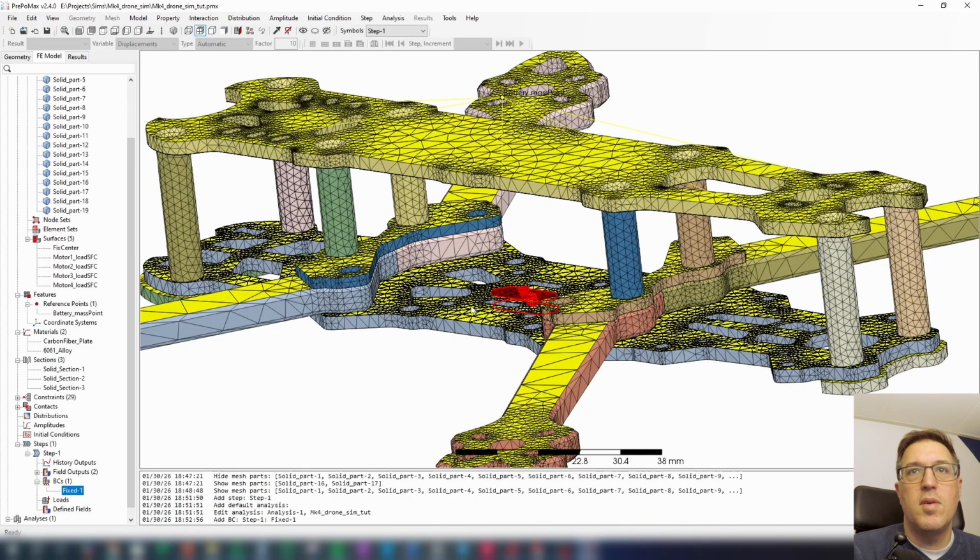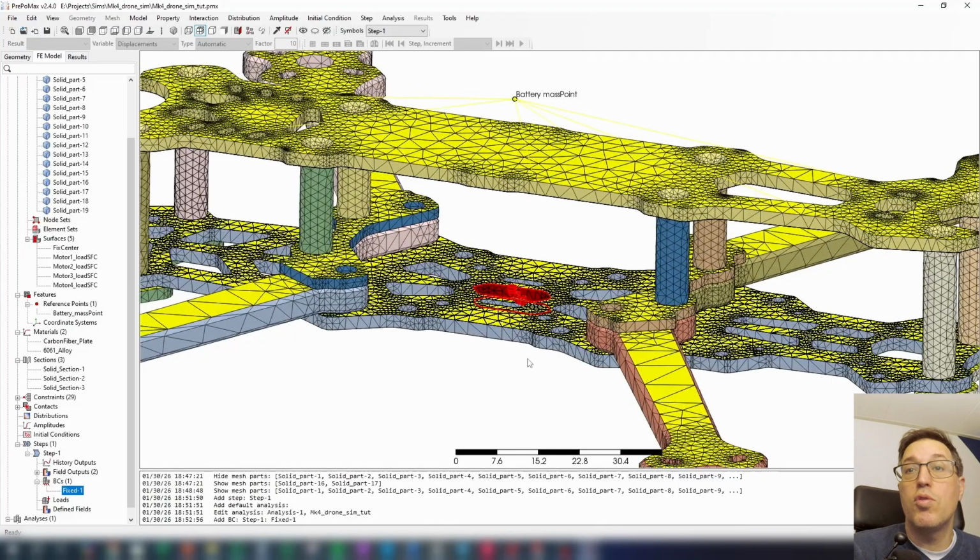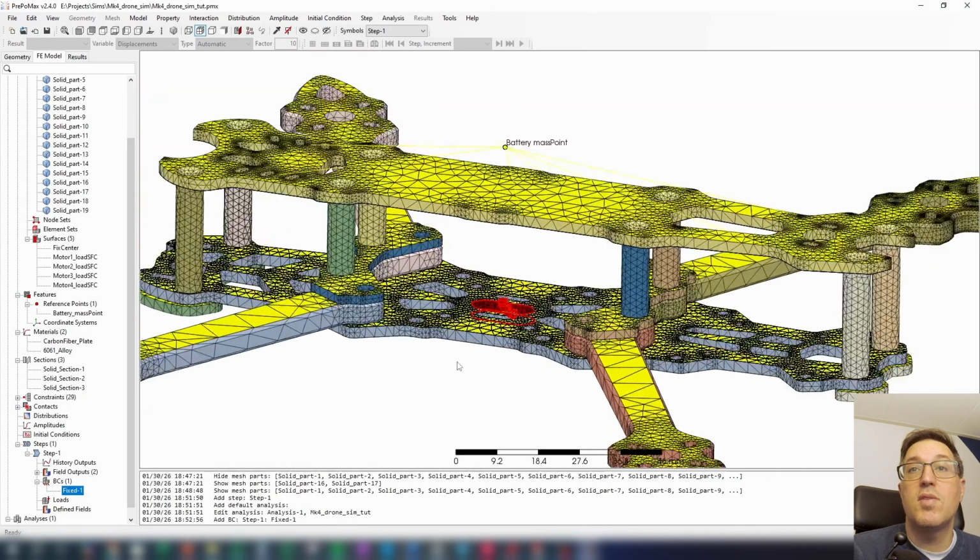If things don't add up in the results of the analysis, which happens, you always need to be judgmental about what you're doing. Okay, never take things for granted. You're doing analysis. This is a tool. This is a guideline. This is not a definitive thing. If something doesn't add up, go back, change the boundary conditions, figure out what you did wrong, or just don't use it if it doesn't make sense to you.